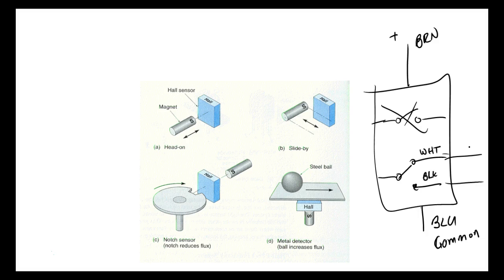So a common can be grounded, but a common doesn't have to be grounded. But most people don't understand that. Like your car, they'll call the black wire the ground wire, and that's not true. That's a common. Your car has a common. It doesn't have a ground, right? But everybody calls it ground.